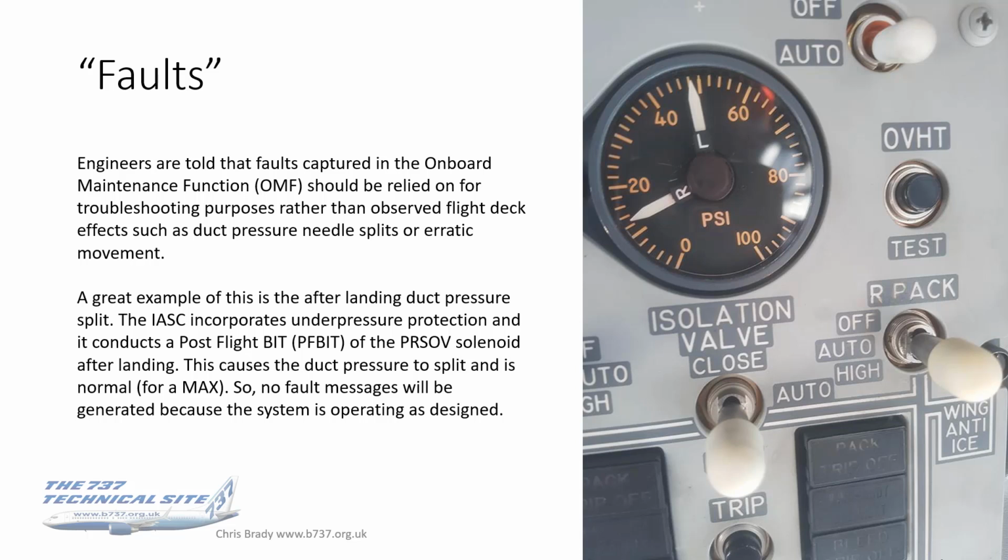Faults. You see, I've put this in speech marks. Now, engineers are told that for the MAX, faults captured in the onboard maintenance function, which I'll describe toward the end of this presentation, should be relied on for troubleshooting purposes rather than observed flight deck effects, such as duct pressure needle splits or erratic movement.